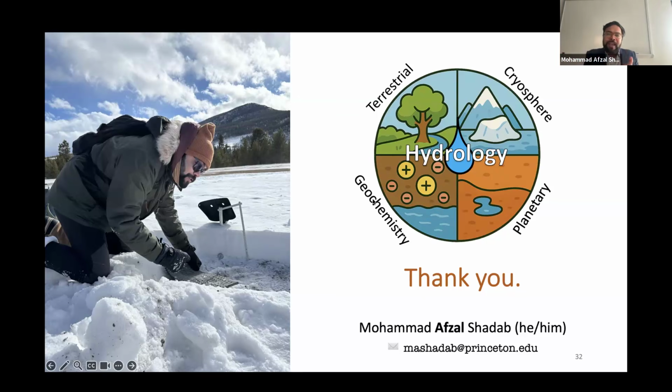Could you use them in your fracture model and simulate fracture propagation? Because some of the melt will naturally go through these cracks and crevasses and end up becoming subglacial fluid. You have these channels below the ice sheet, and the way we are introducing these is at the boundaries. So the second is to do a decoupled but yet coupled modeling of ice sheet fracture and hydrology.